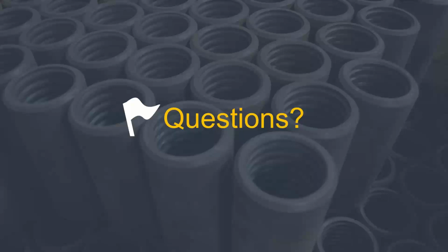I've seen it where you've got, let's say, a 4x4 cap, and then the piles are put kind of diagonal. Now, I don't know if that eliminates any of this teeter-totter. I think when you put 2 opposite each other, you're going to have this teeter-totter effect. I don't know how else to refer to it. But if you put them, let's say it's a 4-foot square, and you put one 1 foot from the end and one on the other elevation, 1 foot from the opposite end, they're kind of like diagonal. Does that help with the teeter-totter or not really?